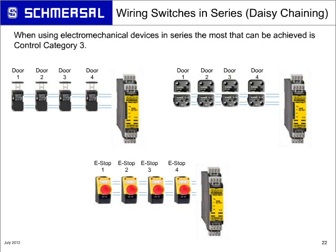In the case of the top left or the top right, you see 4 doors, doors 1, 2, 3, and 4. If a fault occurs on door number 1, let's say the first channel has welded or there was a short circuit in the wiring of that particular switch, if all you opened up was door number 1, the safety relay would detect it.